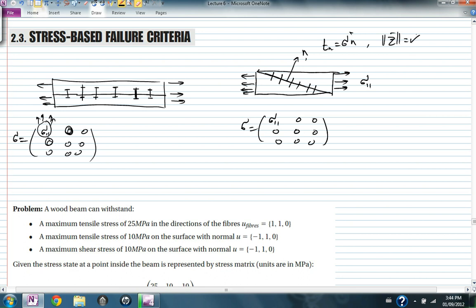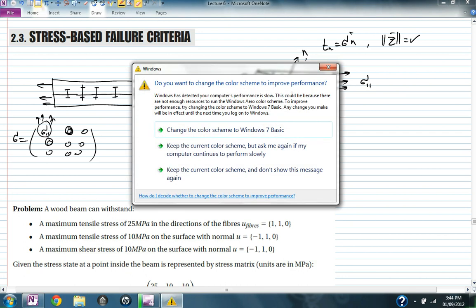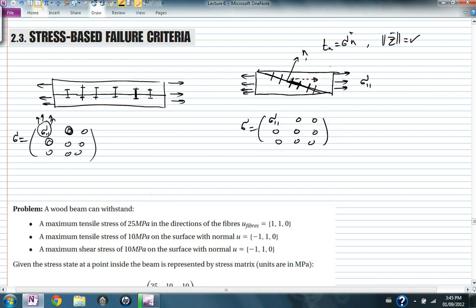So knowing the shear stress on this plane, which is not equal to 0 in this case, because the forces are applied in this direction, so there is a component in this direction. I have to compare it to the critical shear stress, and by comparing the value of the shear stress at this plane to the critical shear stress, I'm able to know whether this material will fail or not, or the shear studs will fail or not.